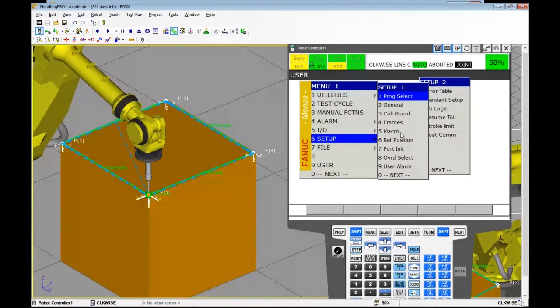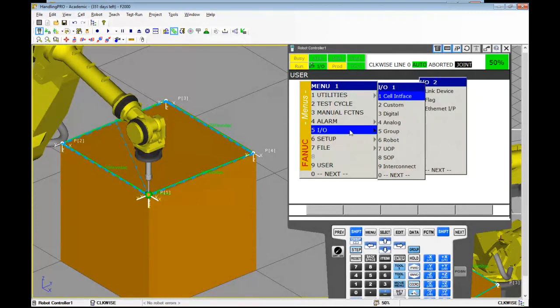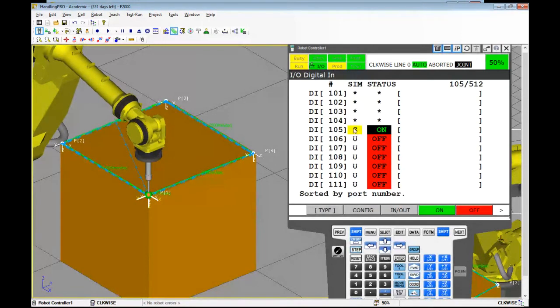So you have whatever sensor is coming on. The idea here is possibly you've got the object coming down the line, and when the object hits the sensor, it triggers something on, and then you can use that to have it go over and pick up the object or something like that. So that's kind of where these digital sensors can be used.